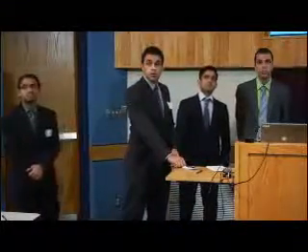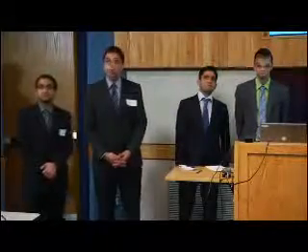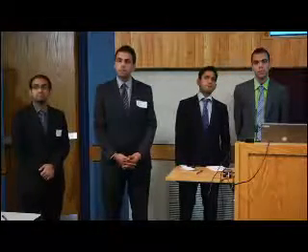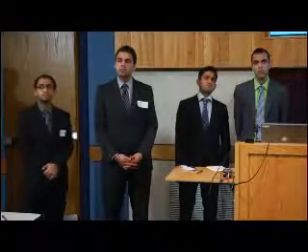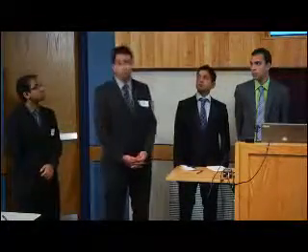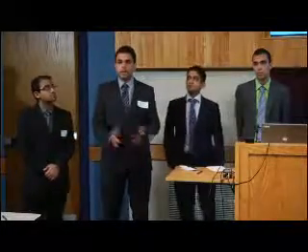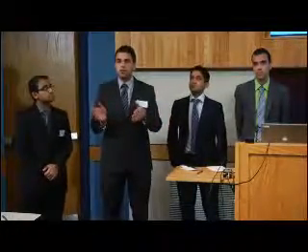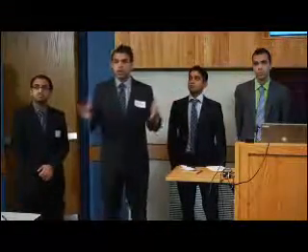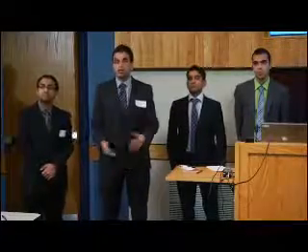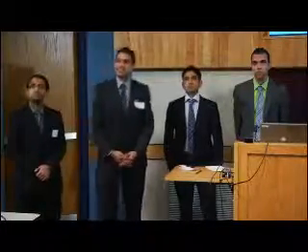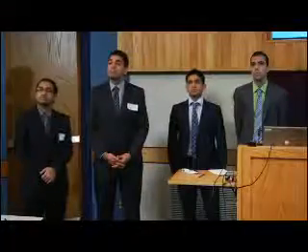So in your economic analysis, you included the cost of the SCR? Yeah. You treat all the flue gas with the SCR, and then in the end you take the slipstream of 1%. That's true, but the SCR has to be retrofitted to the side of the boiler, and because it's a new capital investment, we included it in the plant. But we are hoping the NOx unit would handle 100% of the flue gas, so in the future it would be an equal investment. It's going to be 1% of slipstream.